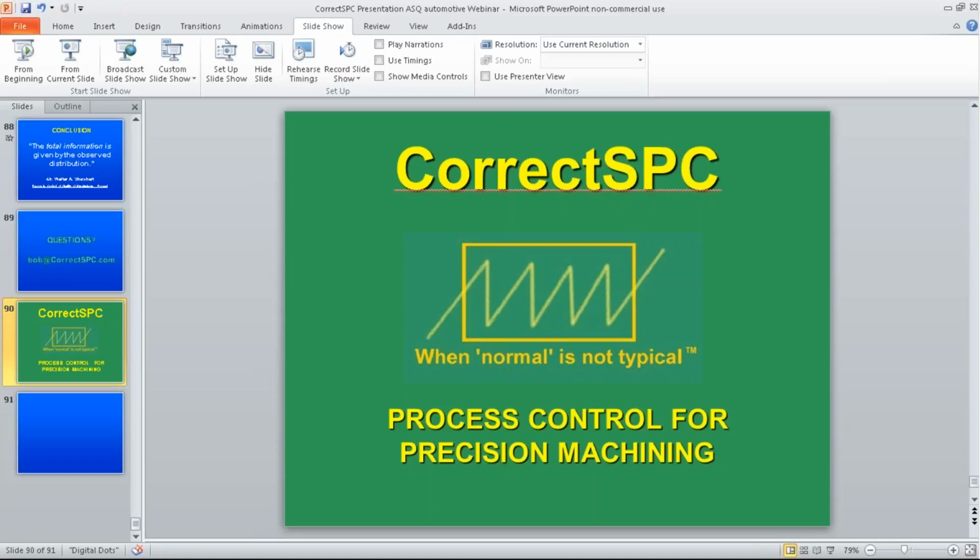Do we use SPC for common causes or special causes? Well, traditional Shewhart charts expect common causes and try to eliminate special causes when they occur. In this particular case, what we're doing is controlling the common cause. We aren't just watching it like you would do with a Shewhart chart. A Shewhart chart just watches it like noise and waits for a pattern to occur. We have a pattern. We're just trying to control the pattern in an area between the specifications. So it's a little different thought process than what they're doing with a Shewhart chart. And that's why we call it a non-Shewhart methodology.